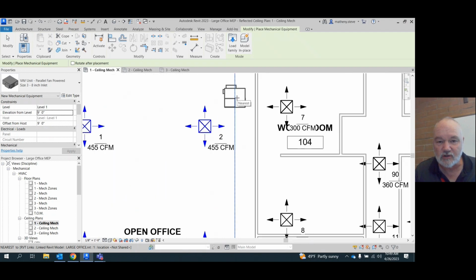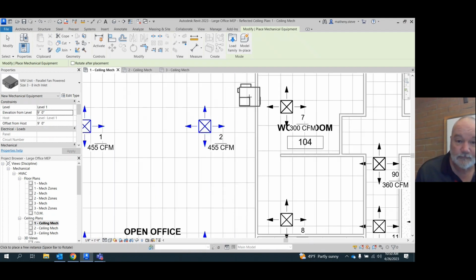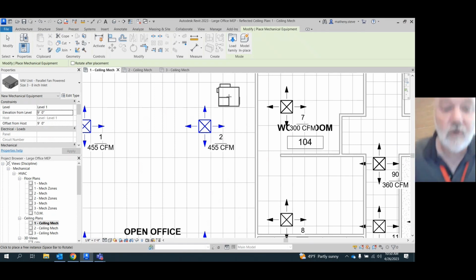Zoom in here because I want to show you a couple things about this VAV fan. First of all, there's your 8-inch inlet. The 8-inch inlet is on the upper left side of the picture that you're seeing, because I'm recording this, I can't point to something because I can't see you. On the bottom right side, you'll see a little outcropping. That is going to be the outlet, so that needs to point towards where we want the air to go. The 8-inch inlet, which is on the top left, needs to point where we want the primary duct.